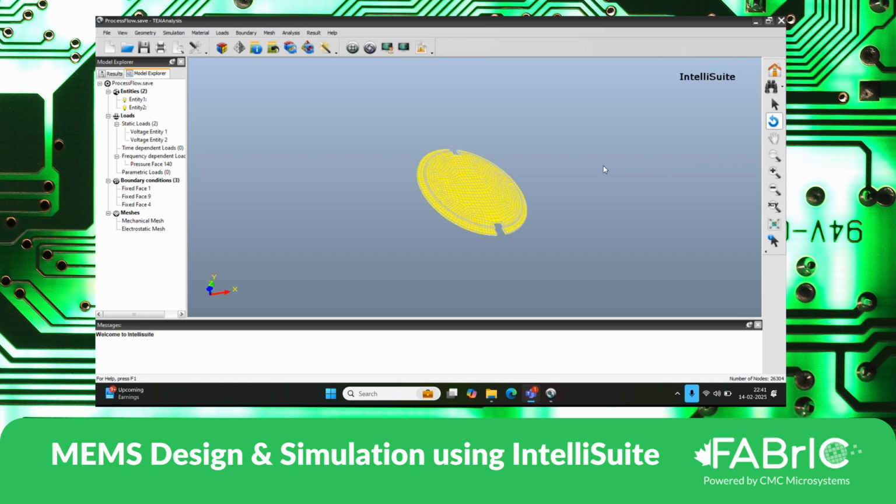The output of the sensor has to be made readable through an ASIC. ASIC is technically a too complicated term, so let's use the word ROIC. For a ROIC, a readout integrated circuit, there are 2 ways of doing it. We fabricate the MEMS device and, using the wire bond, we can give the feed to the discrete component level circuit also.